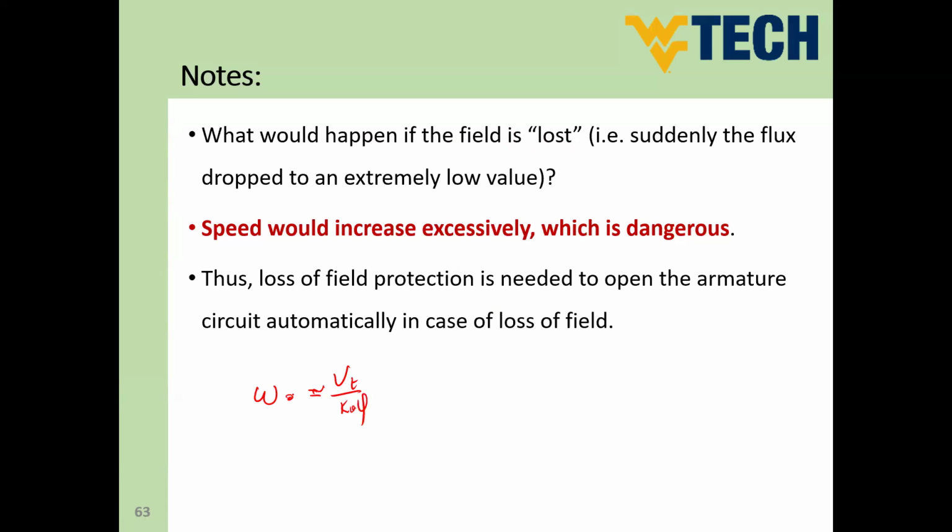So during motor operation, if you lose your flux, theoretically the speed is going to be infinity, which means the motor will overspeed until damaging the motor bearings.